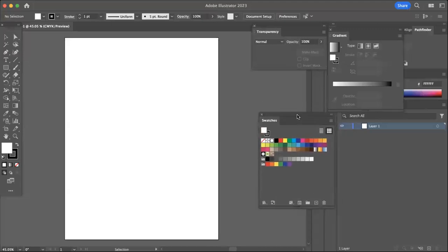So the nice thing about layers is you can go down to the lower right-hand corner, right at the bottom, and create a new layer. You can work and draw on one layer, and then you can lock it. You can see there's the little eyeball. Beside the eyeball allows you to lock whatever work is on that particular layer, which is very handy when you are doing drafting and you need parts of the drawing to stay in place. So for the moment, I'm actually going to stay on layer one and set up my drawing tools.